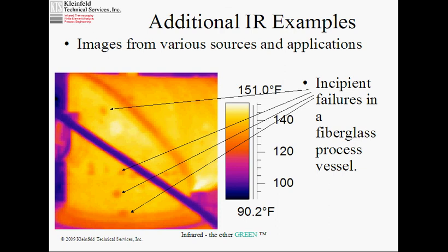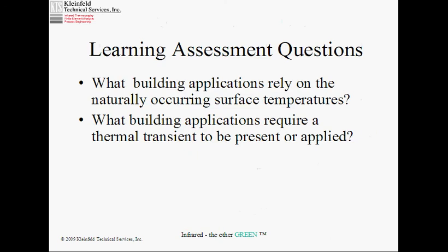You were getting delamination, so there was either a bubble with air, or a bubble that had burst and filled with product, in this case pulp, which was more insulative than just the wall, because you had wall plus however many inches or fractions of an inch insulating it, and therefore was keeping the heat. You know, this spot is better insulated because it's got crud in the way, or an air pocket. So this is a failure.